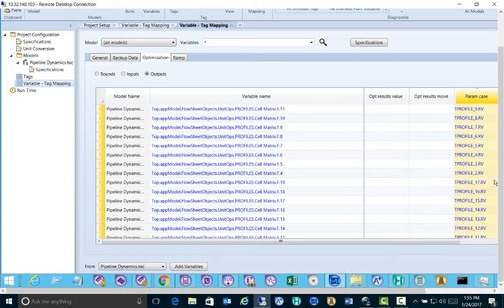In this demo, the key plant measurements for model inputs are gas temperature, model flow, and compositions from gas platforms. The pressure measurements at the inlet of the gas plant are also available and taken as model inputs. The primary model outputs are pipeline temperature, pressure, and condensate holdup profiles along the pipe distance. A few KPIs such as the gas volume index at the current conditions, a total condensate holdup, and hydrate formations are also exported as outputs.